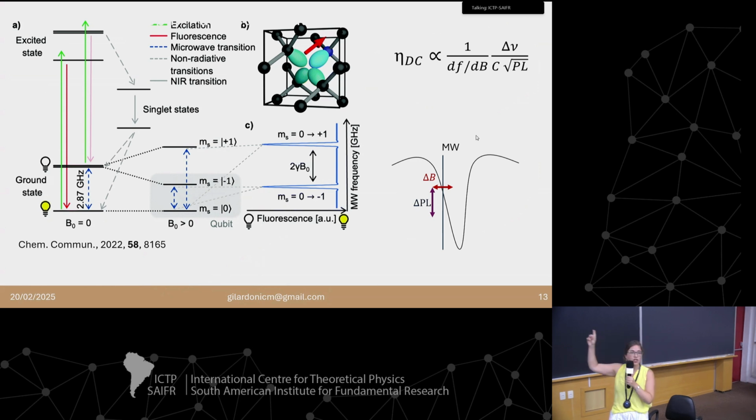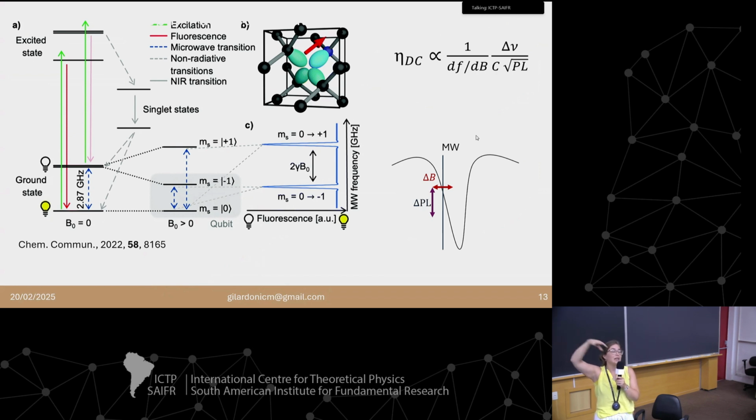So the image I showed at the very beginning is a scanning probe with a SQUID at the tip, and you can reach a couple of nanometers of resolution. They are very sensitive in terms of what magnetic field they can sense, but they need to operate at cryogenic temperatures, right? So there's always one trade-off that you need to overcome.